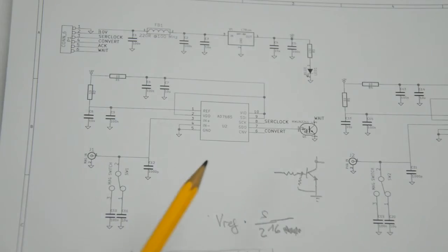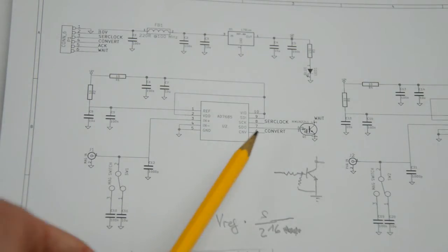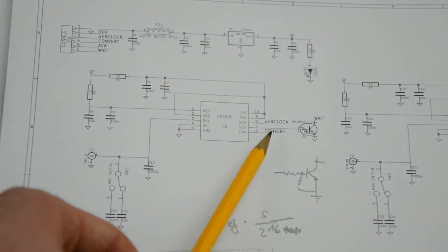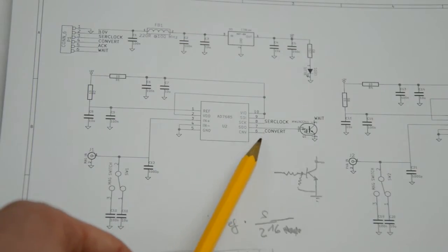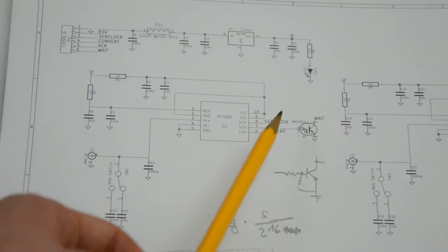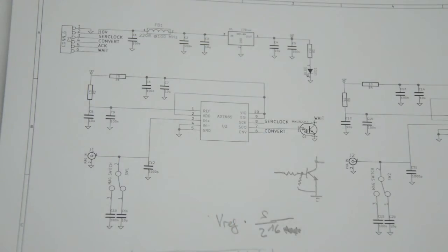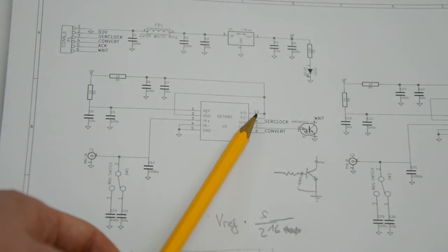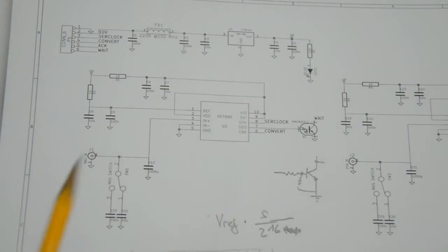But anyway, on the digital side here, you tell the ADC to take a measurement by giving a pulse on that convert pin here. This is done on the computer, going through the control board that we discussed last time, and eventually ends up here. When the ADC gets this pulse, it takes the measurement, and then you can use this serial clock pin here to shift out the 16 bits of the measurement